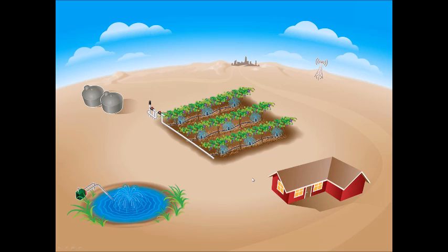So the typical way without Ranch Systems is that a grower would have to come out and make sure that the tanks are filled up, that the water level in the pond has sufficient water level, and turn on the pump only after making sure that they opened the block valve first.